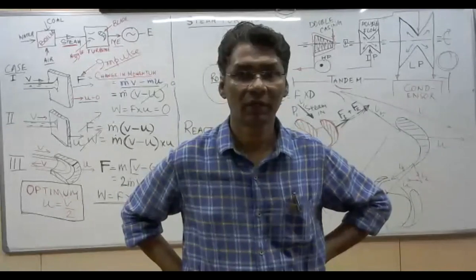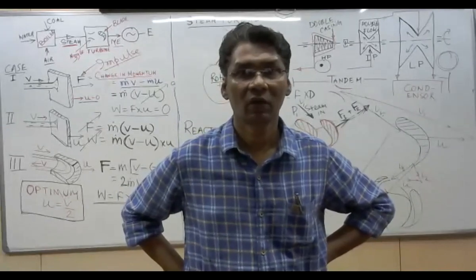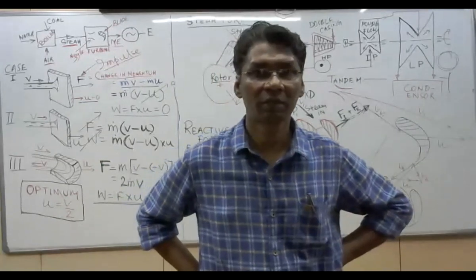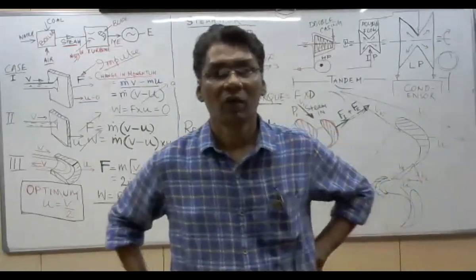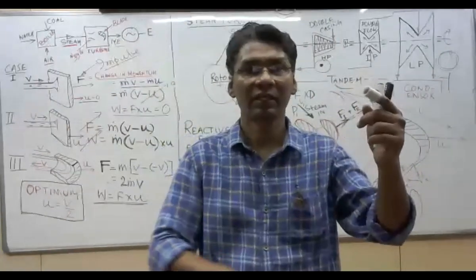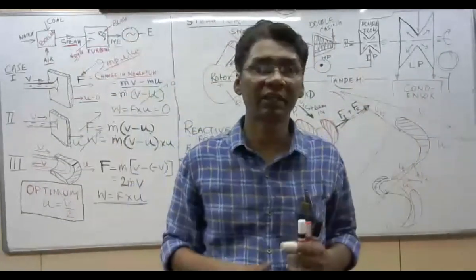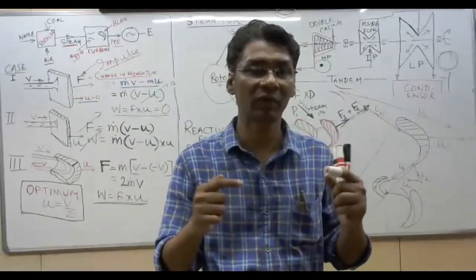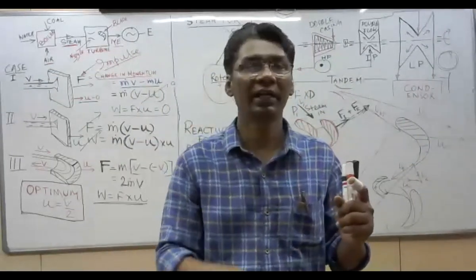Why are holes present in the blades? Holes are present in the blades to connect the blades together for increasing stability of the blade at high speed. That is called lacing wire. Lacing wire is placed into the hole and it connects the blades together.